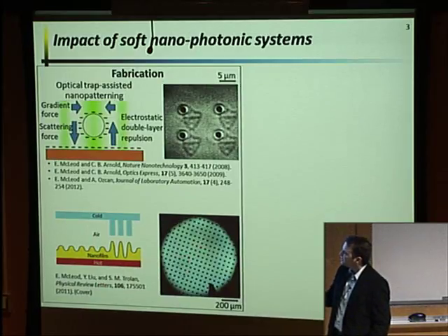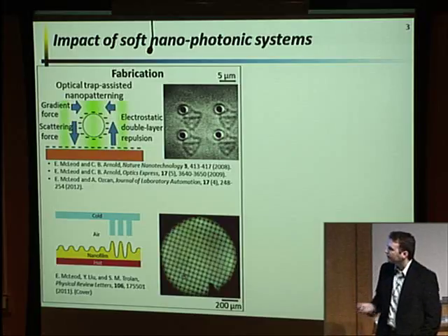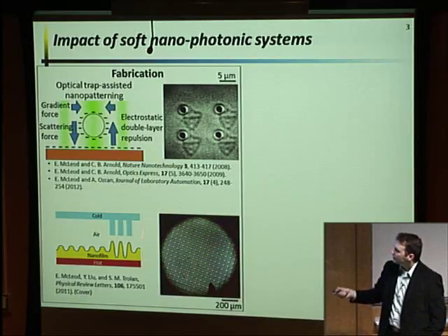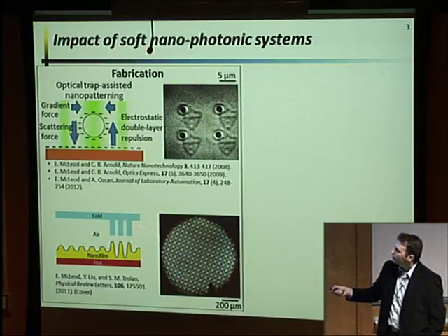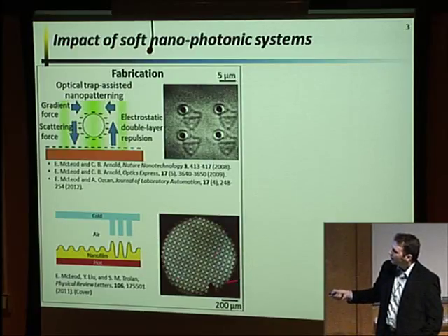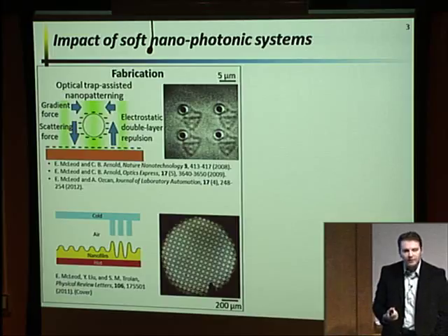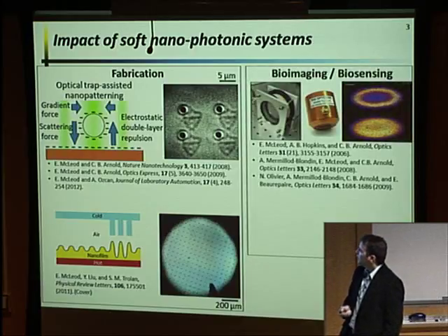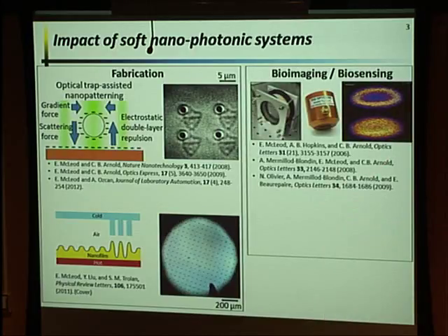This leads to a destabilization, or an instability, in the polymer film. So rather than remaining flat, it spontaneously forms these ripples. And we can seed where these ripples are going to be formed if we structure this top plate. This would be an example where we're creating something like a microlens array. So this is an array of small bumps on a surface that could be used, for example, to focus light.